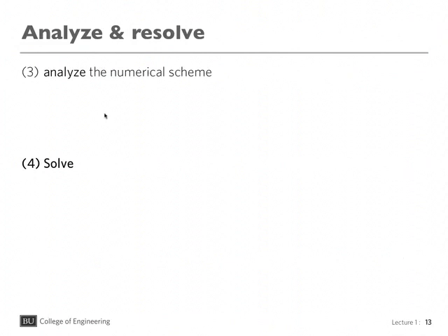Really, all numerical methods must satisfy a certain number of conditions to be acceptable, okay? We use the word numerical scheme. I was saying that the discretization of the model is converting all of your continuum mathematical operators, such as the partial derivative with respect to time, into arithmetic operations. That is done via the numerical scheme.